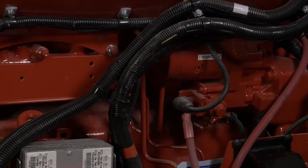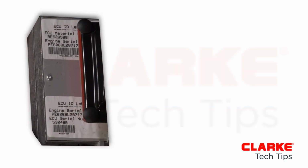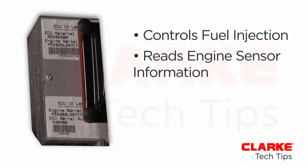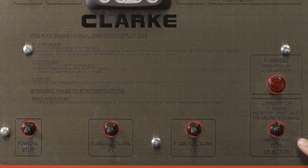Clarke electronic engines are controlled by the Electronic Control Module, known as the ECM. The ECM controls fuel injection, reads engine sensor information, controls actuators, and maintains engine speed. The ECM selector switch allows you to select the primary or alternate ECM. The engine will initially be in the primary ECM selection.